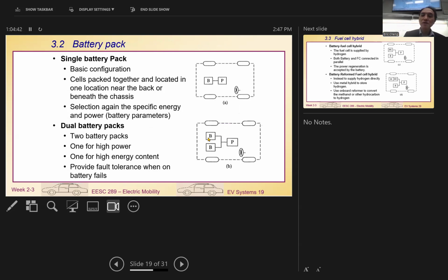So for more detail, I talk about here. That will be battery, connector, converter, but then multiple batteries here, maybe more than one. Then how we pair them up to do the job. Sometimes we can select different kinds of battery. Some of them we can use for high energy content, and some of them for high power. Because for battery, you have different Ah. Then you can select high Ah, which will provide you high current or so-called high C rate. High C rate will be expensive, so you cannot use all your battery at high C rate.